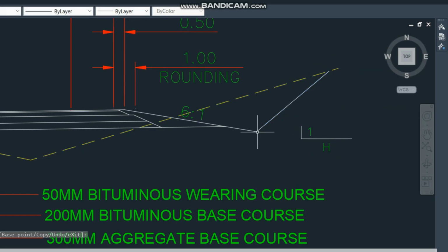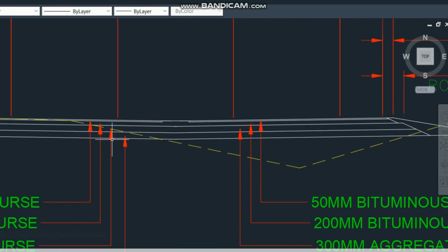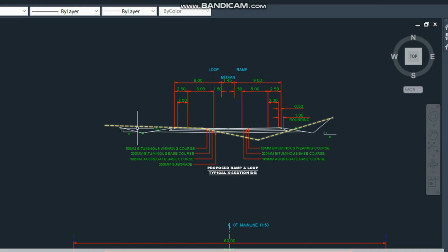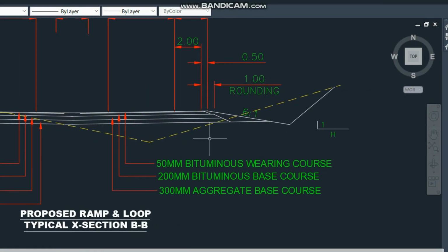So let's discuss these one by one. The first is the daylight basin. If I click here and click any of the corners here, it asks me for input. It's like there is a basin inside here, and then the slope toward the cut or toward the fill.